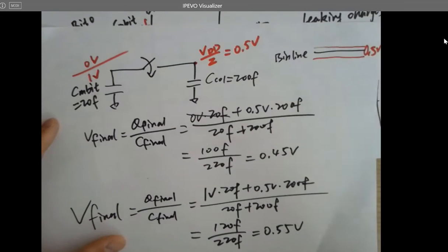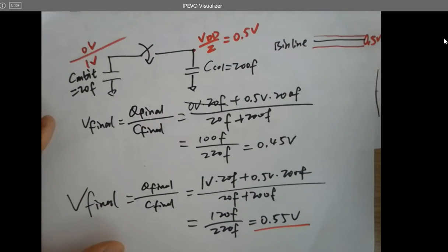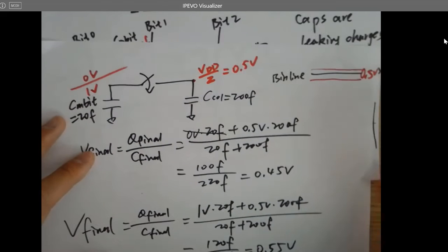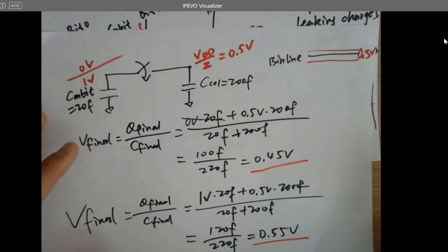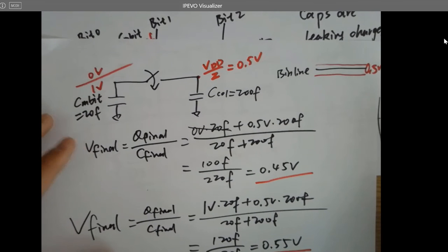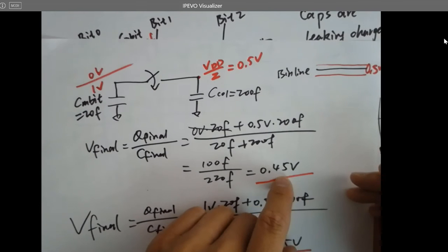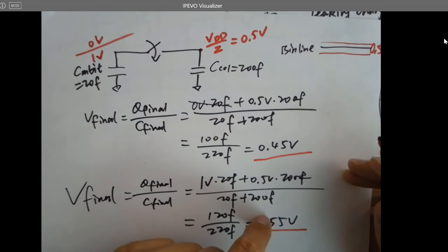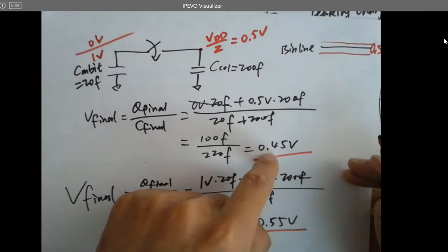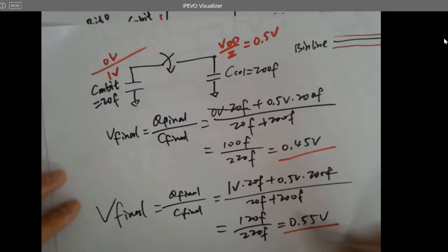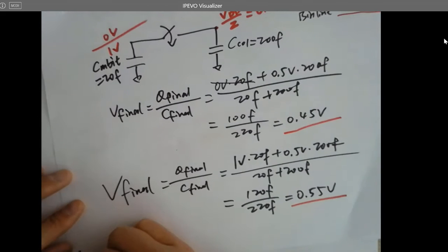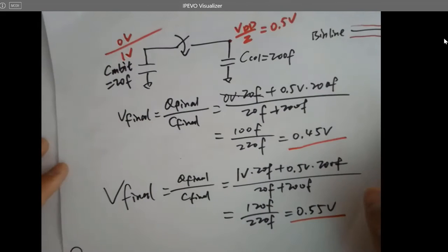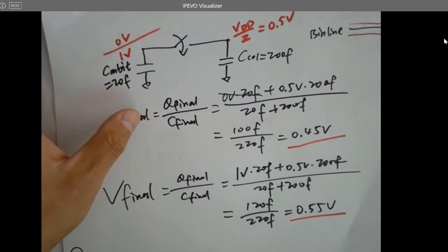Whenever you got this one, you want to pull it right way up to VDD. Whenever you have this, you want to pull it way down to the ground. So you're done. It's definitely not 0, but since you can tell the difference, I'm going to define this one as 0, this one as 1. So now you need a sensing circuit. You just need a sensor, right? Whenever you have 0.45, you sense it and give a 0 to it. So what does the sensing circuit look like?